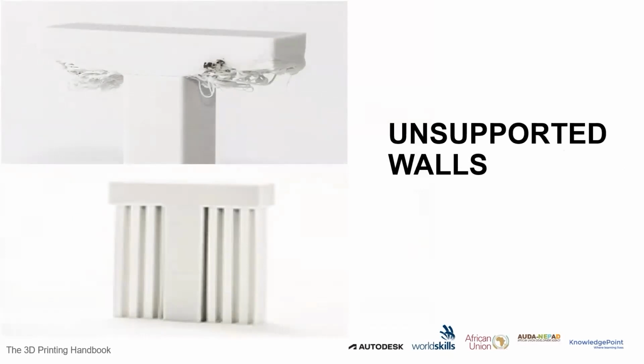Now, there are also certain things to draw our attention to when we talk about support. This is a really perfect example of unsupported walls, not printed with support, and the ones printed with support. You're seeing that it's coming out fine. Just know that the surface where the support is attached will come out rough. So the best way you could have printed this is maybe to print with this part on top, turn it upside down, and you can have a build without any support.